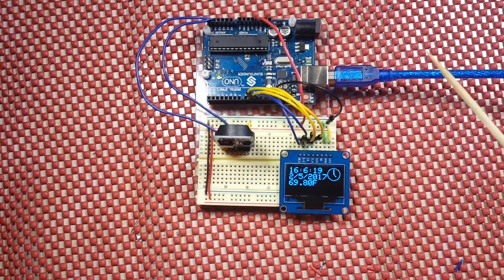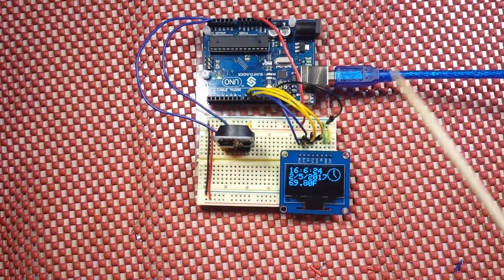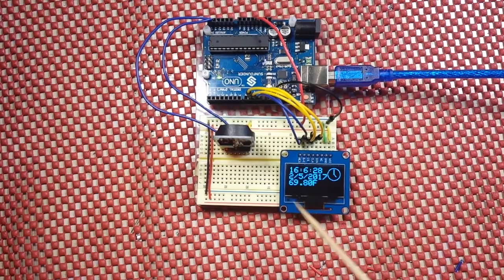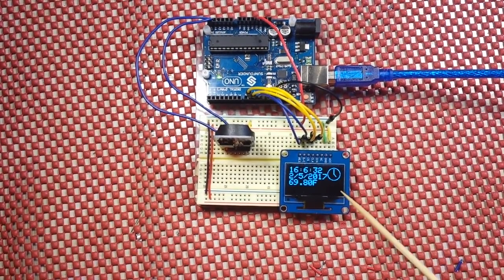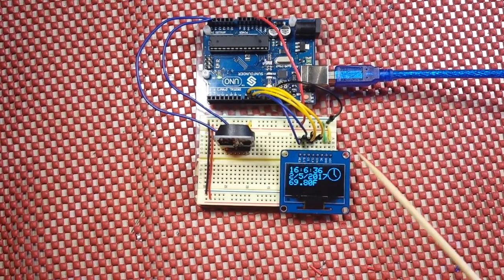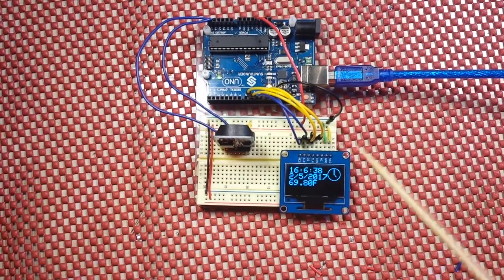Pretty cool. Just remember how that display.drawBitmap command works. You can put any size image that will fit in the memory anywhere on the screen by specifying the XY start positions, the XY size, the color, and the name of the file.